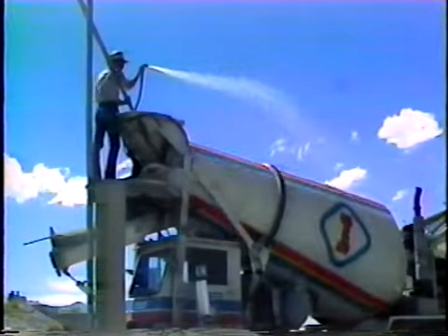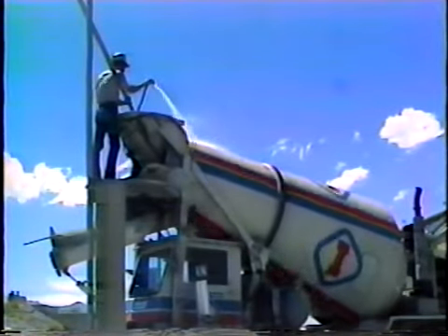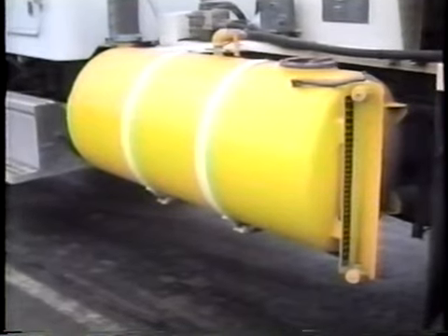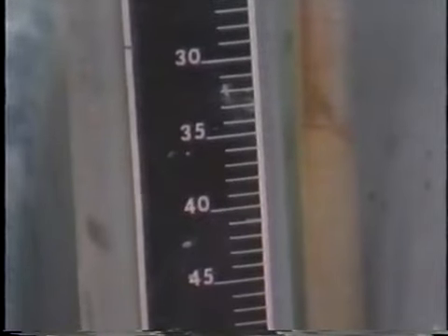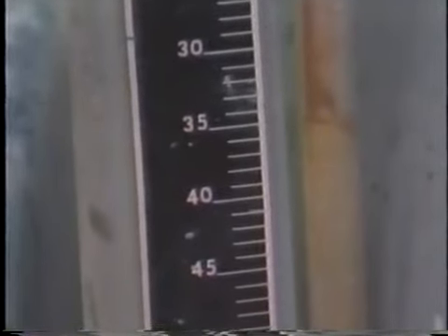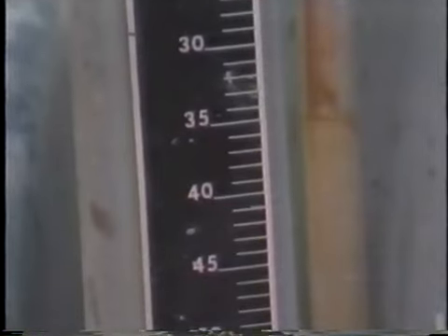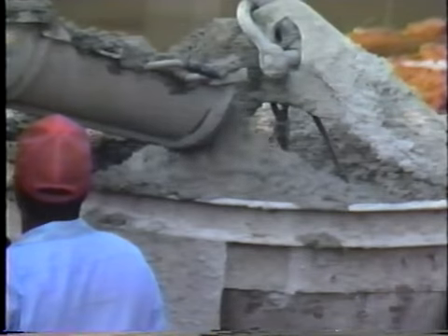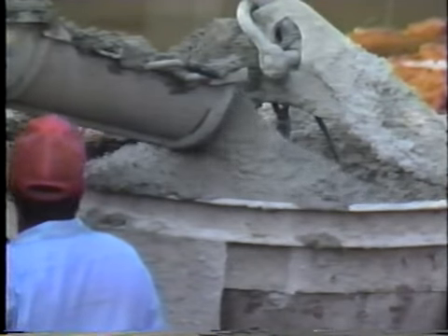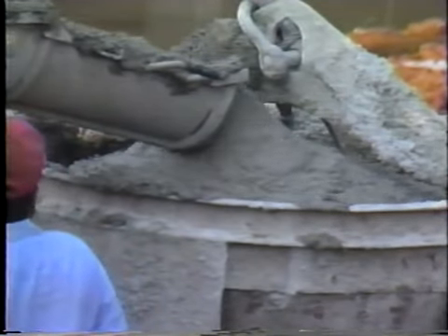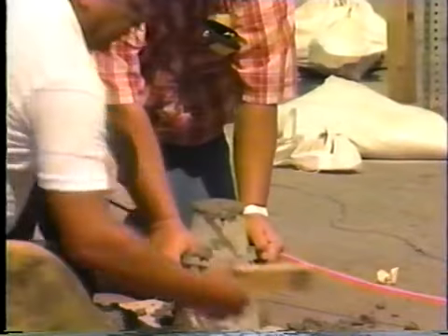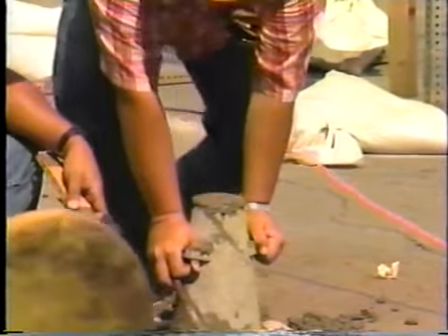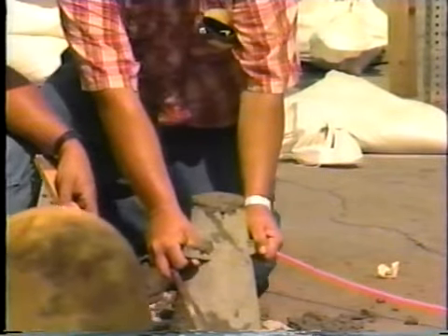For example, if wash water was left in the truck before it was loaded, the mix may be too wet. Or the truck driver may decide to add water if the mix begins to stiffen. So it's important, and it's required, that the quality of the concrete be verified before the concrete is cast. Verification is provided by conventional controlled tests performed in the field.